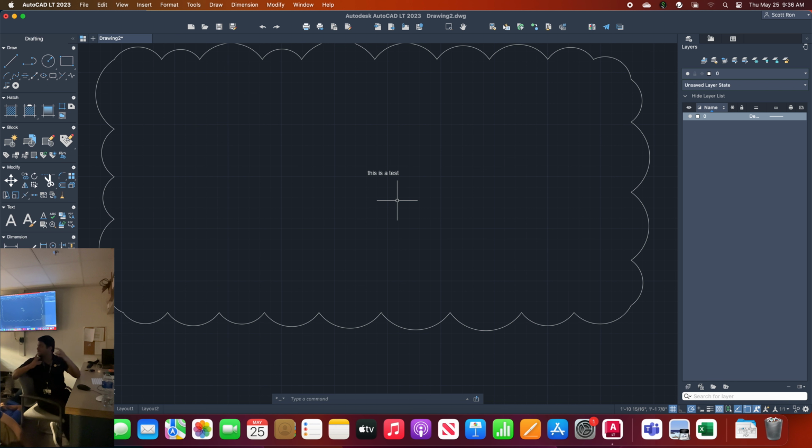Basically, when you're making modifications and you want to put notes, why use clouds? Why not use a different kind of box? Clouds basically mean thought, like a thought bubble in comic strips. If you're looking at a drawing and you see clouds, you will automatically know, oh, there's some notes over there that I should look for. There's something written over there. The shape is trying to show that it's an idea.